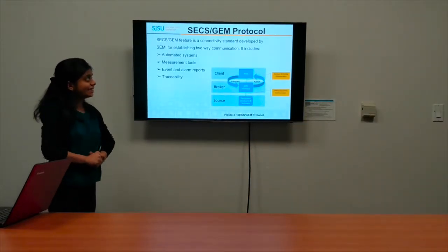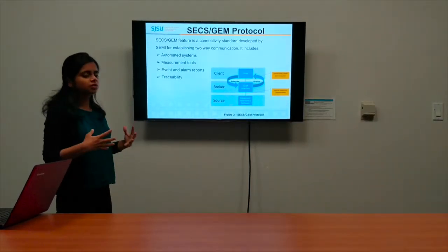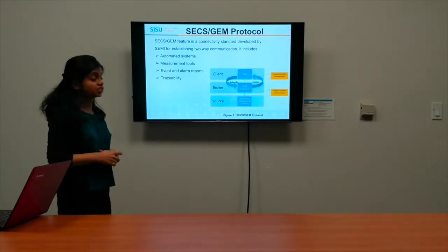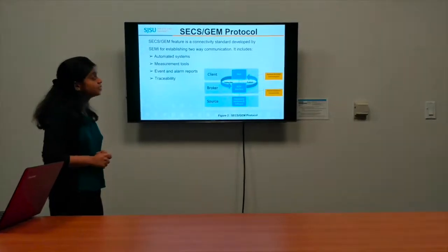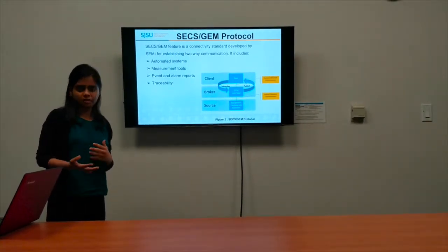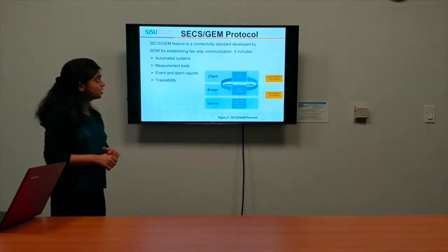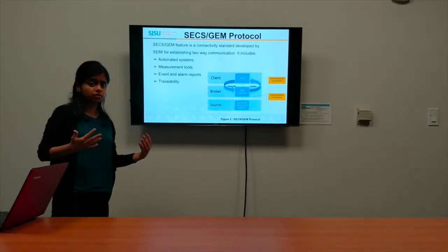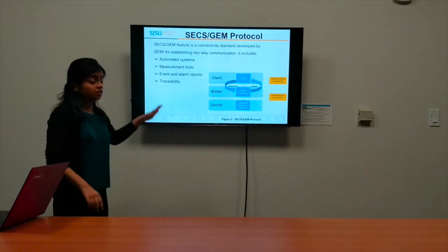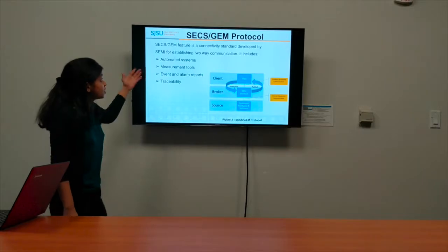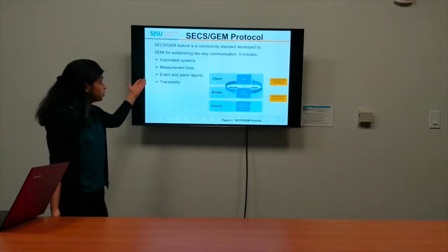So what exactly is SECS/GEM protocol? Going into the literature of it, it's actually a connectivity standard, and it was developed by a non-governmental organization called SEMI. They are based in Milpitas actually, and it enables two-way communication between different machines. It gives us excellent features, like helping us build automated systems.